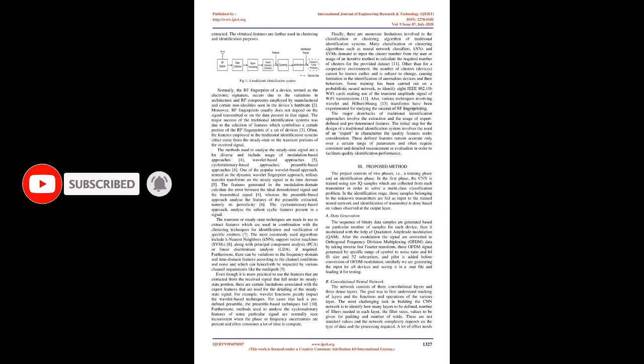One of the popular wavelet-based approaches, termed the dynamic wavelet fingerprint approach, utilizes wavelet transforms on the steady signal in its time domain 5. The features generated in the modulation domain calculate the error between the ideal demodulated signal and the transmitted signal 4, whereas the preamble-based approach analyzes the features of the extracted preamble, namely its periodicity 6. The cyclostationary-based approach analyzes the salient cyclic features present in a signal.